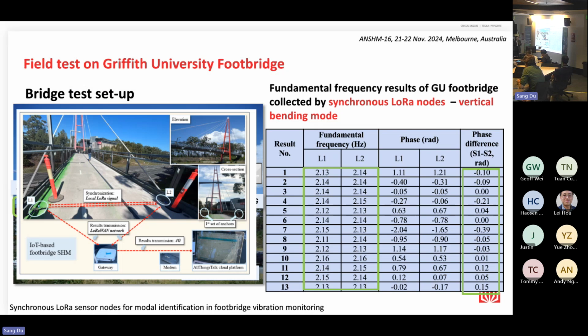Unfortunately, this bridge hasn't been reported by anyone, but students can actually feel the vibration, the wobbling motions on the footbridge when walking on it, especially in severe weather like wind and heavy rainfall. Its design frequency from its design report is also 2.2 hertz, so it's very close to the walking frequency of pedestrians.